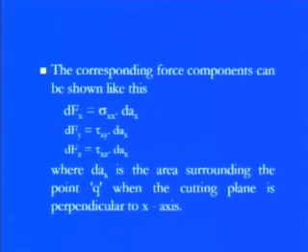Okay, so now you see here, as far as the force component in the x direction is concerned, we have dFx is sigma xx into dAx. That means in the x direction we have normal stress because of the perpendicular axis, but the other two force components, dFy and dFz, are not perpendicular to the area concerned. So here the normal stress components are not being set up within the object or outside of the object, that means the surrounding part.